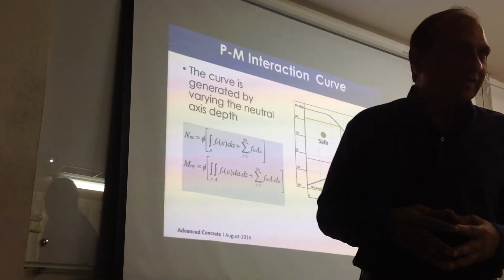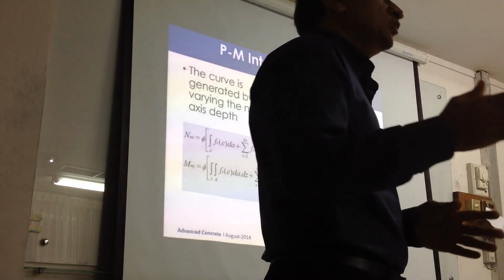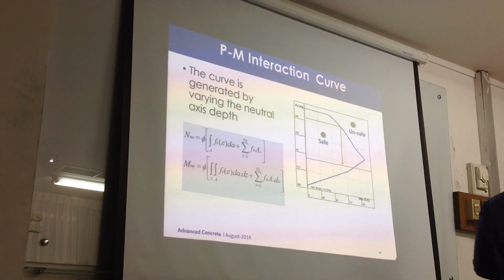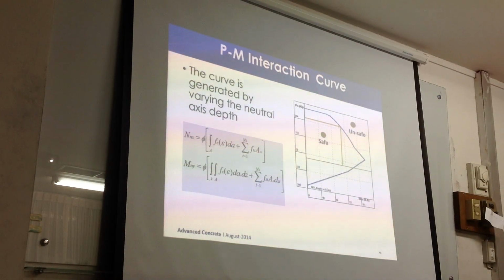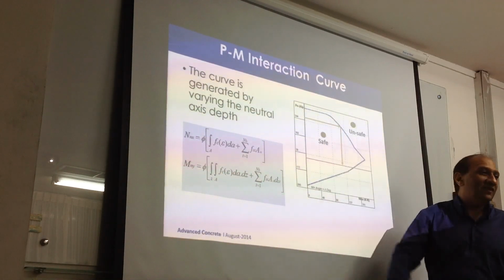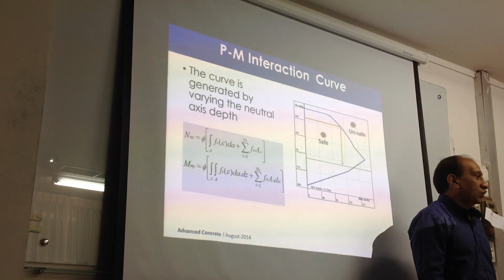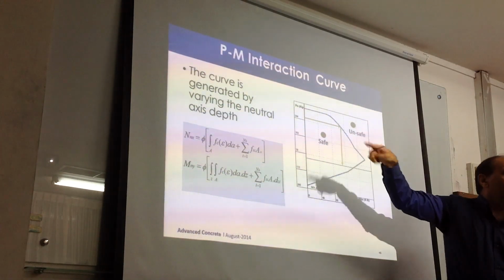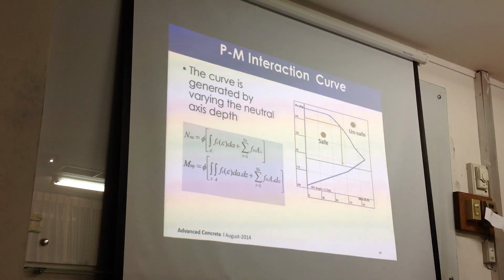And then if it's a nonlinear case, every time step has to be 100 nonlinear steps. So 30,000, there you go. We are dealing with a very large number of loading conditions. So generating the capacity curve one time is very helpful because that does not change. Only the loading changes. So we keep checking each case, 4,000 times. If 1 out of 4,000 is not okay, the column fails. Because it must satisfy all of them, not some of them, not 90% of them, every one of them.